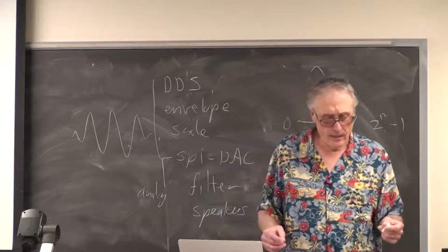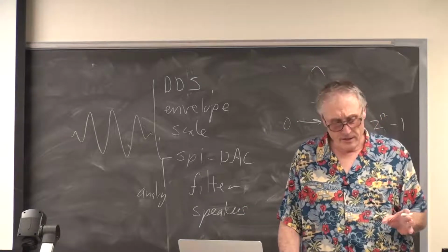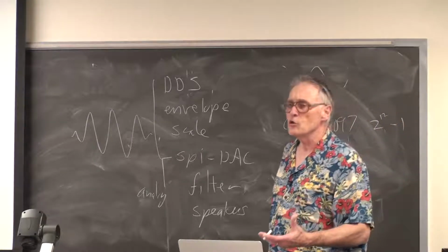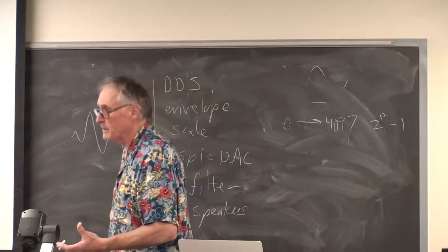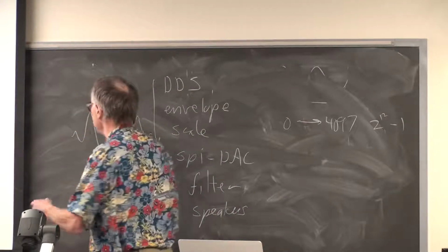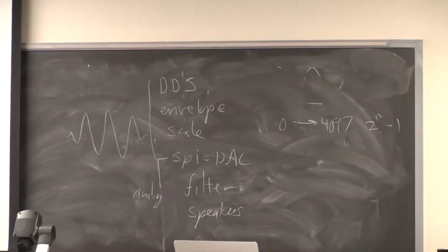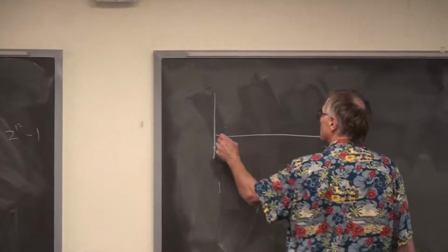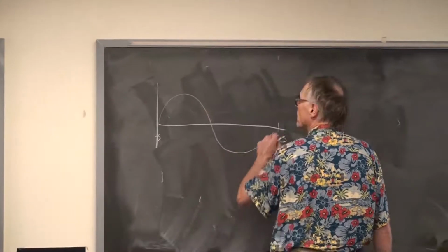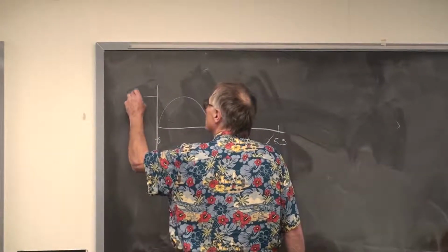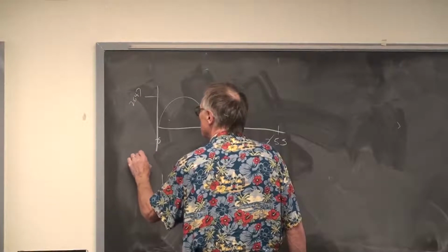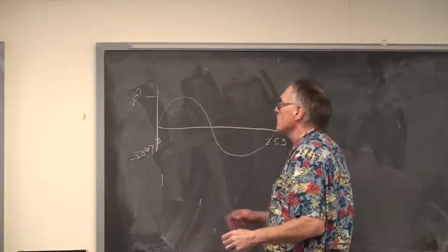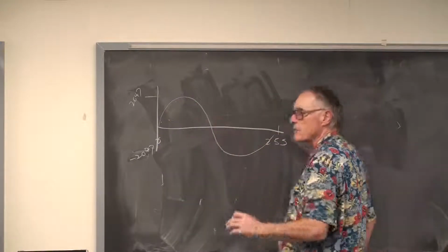So let's start with some direct digital synthesis. The goal here is to figure out how to optimally choose entries from a table of sine. So you're going to have a table of 256 sine values, corresponding to index 0 to 255 will be 2 pi. We'll scale to 2 pi. And the amplitude you're probably going to want to set to like 2047 plus or minus 2047. And what you'll have here then is 256 samples.